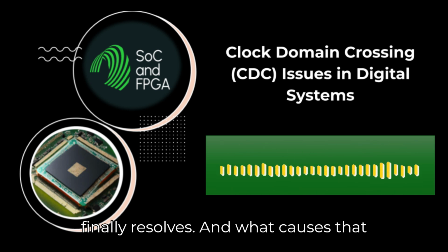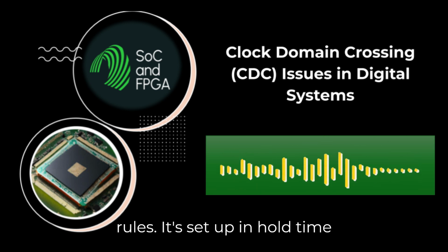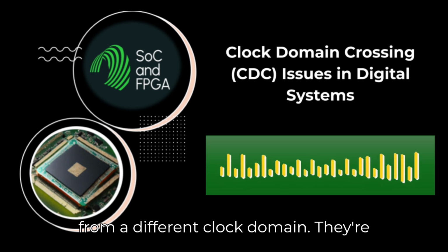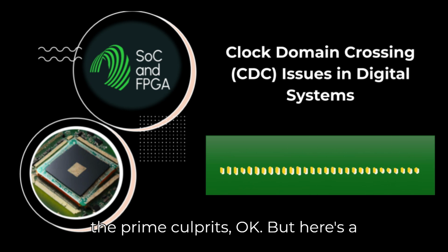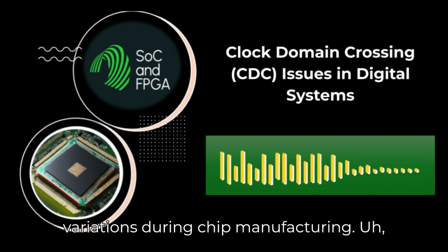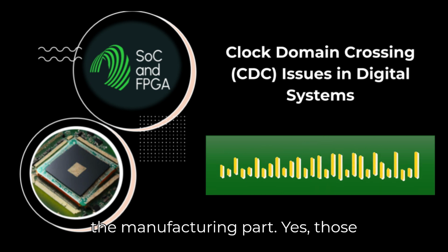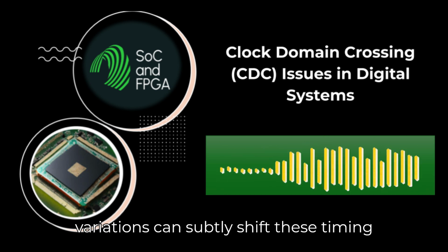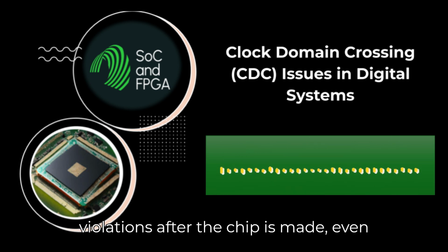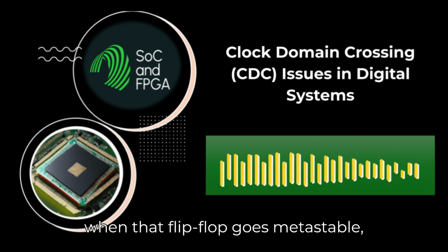And what causes that collision? The core cause is a violation of the flip-flop's fundamental timing rules, its setup and hold time requirements. Asynchronous inputs coming from a different clock domain are the prime culprits. But here's a really crucial detail. Even in designs that look perfect on paper, tiny variations during chip manufacturing can subtly shift these timing windows. So you can get setup and hold violations after the chip is made, even if the design looks fine beforehand. And when that flip-flop goes metastable...